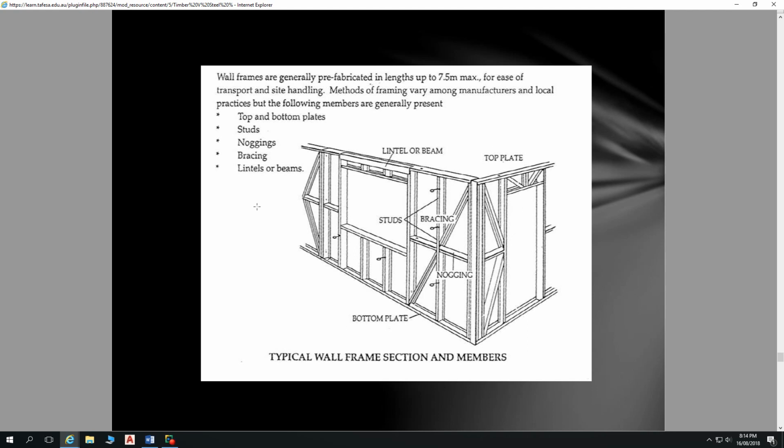Essentially, we are designing boxes to transfer load and provide this thin structural aspect, a 90 wide or 70 wide structural aspect for fixing our internal linings to and to support our brickwork. It's doing the same thing, hence we have a lot of the same members. But something that you now see a lot more in your light gauge steel framing are elements like this, which are essentially trusses. Something like that is actually a vertical truss.